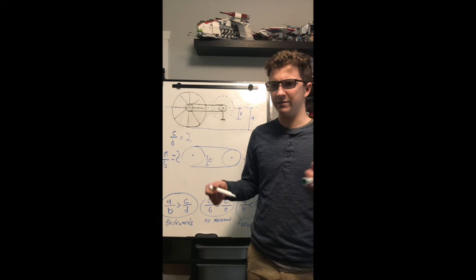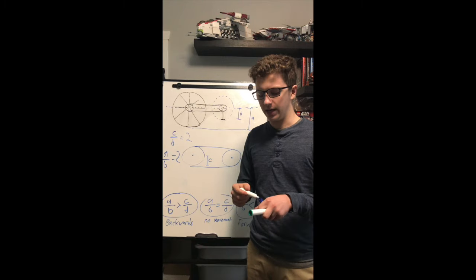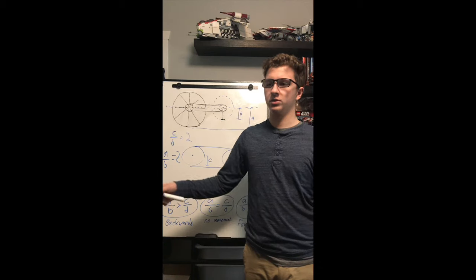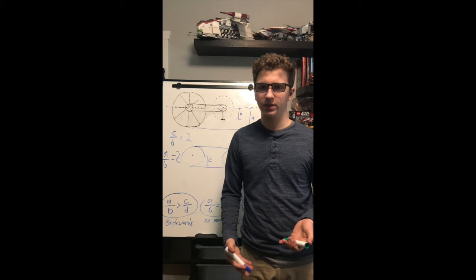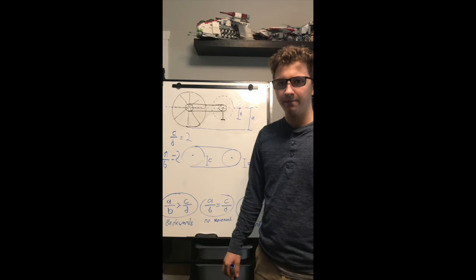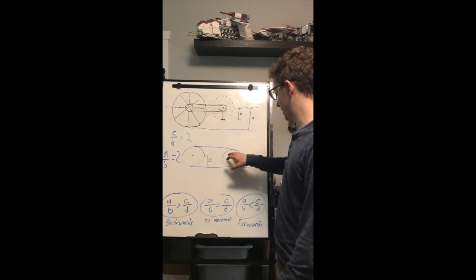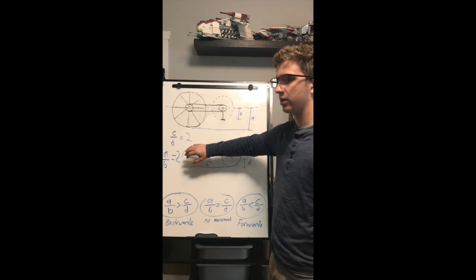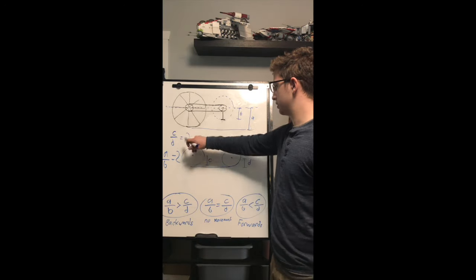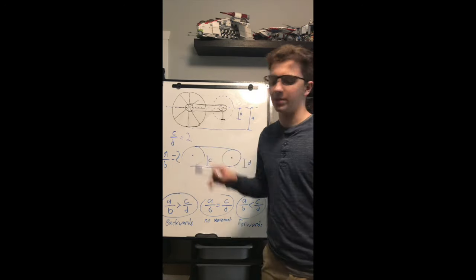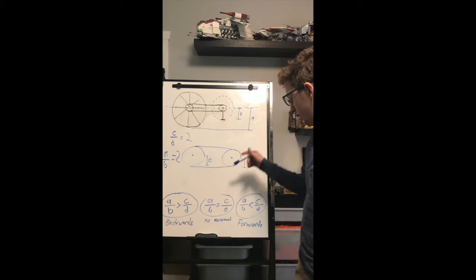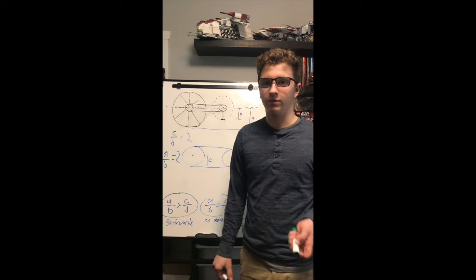Now obviously this would be very hard to recreate in the real world. It's very hard to get exactly the same gear ratios, and there's always going to be small alterations resulting in small movements. But theoretically, if they were exactly the same size, there would be no movement. Now, if the size of C is greater than twice the size of D, that would mean that C over D is greater than 2, therefore greater than A over B, and the bike would move forwards.